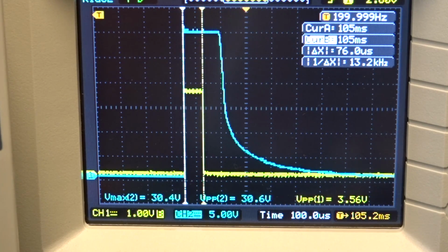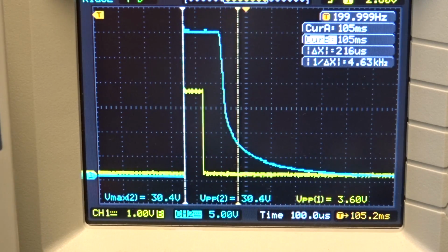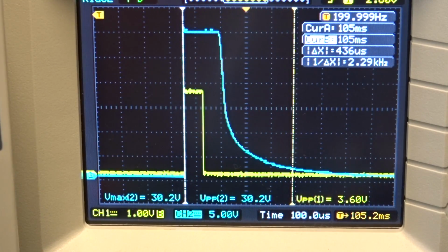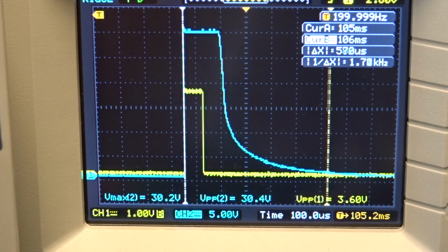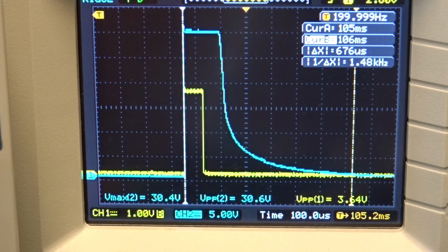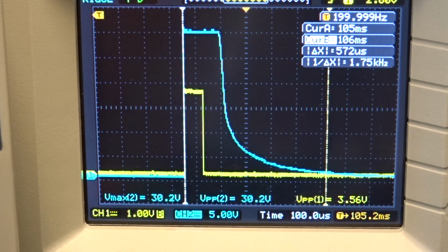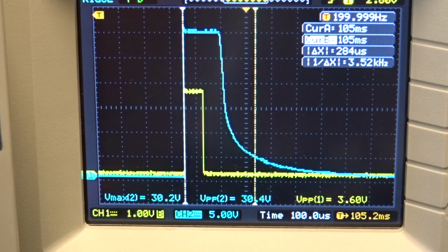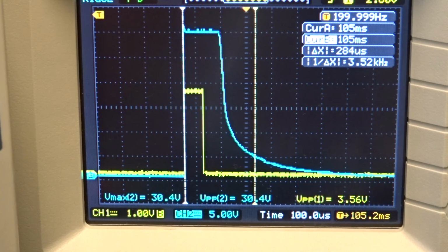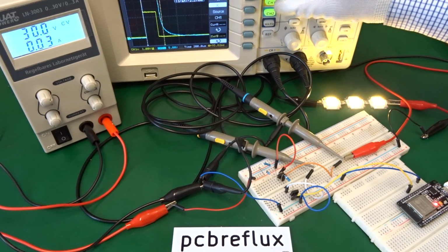So this circuit is maybe not able to switch more than 1 kHz, or as you see, 1.5 kHz maybe is the maximum. But this really depends on the usage of our resistors. Every resistor and the internal capacitance of the N-channel and P-channel MOSFETs build an RC circuit, and this is what we see here. So the charging and discharging of the MOSFET gates limit the switching frequency.